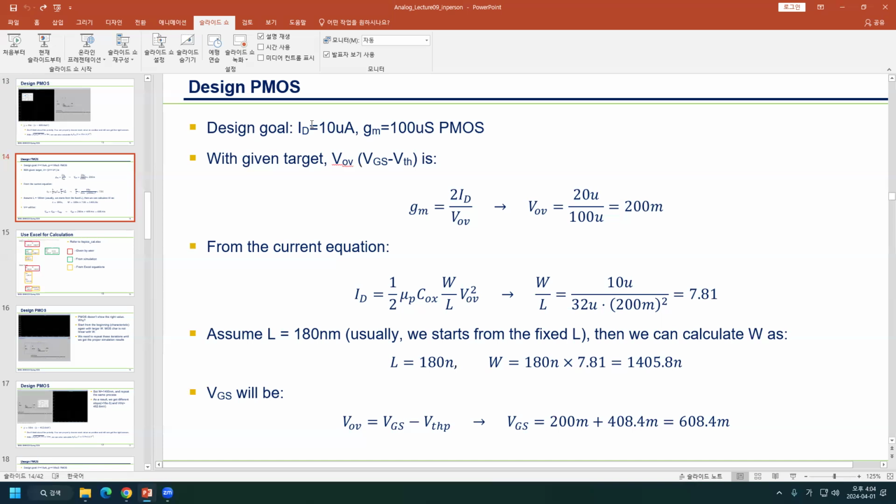10% mismatch is what you need. You make 1 meter of MOSFET, and then 10% is what? 100, no, 10 centimeter, right? That's really easy. You're not going to miss the 10 centimeter variation. So if you make things large, it's highly likely you get an accurate number in terms of ratio.